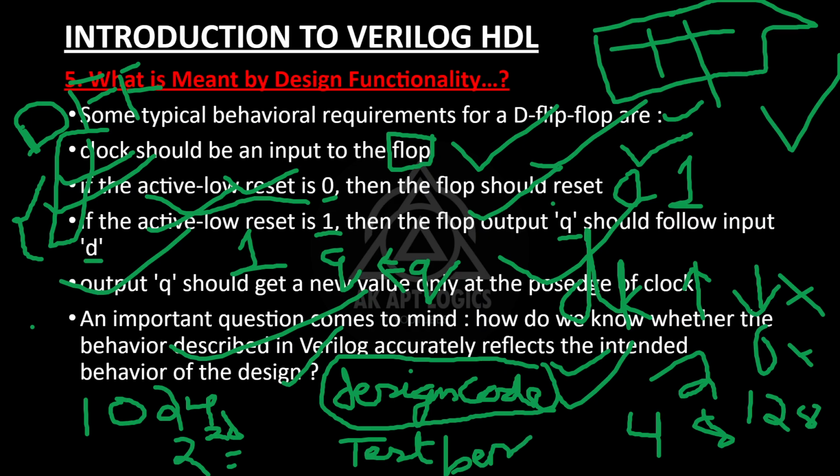The functionality of our digital system design. In this case, we are going to describe the functionality of the D flip-flop, right? Similarly, the test bench is required to test that D flip-flop by applying some inputs. Those are called test vectors. Those won't be called inputs, but for the sake of understanding I am saying inputs. You should say test vectors, test cases or scenarios.